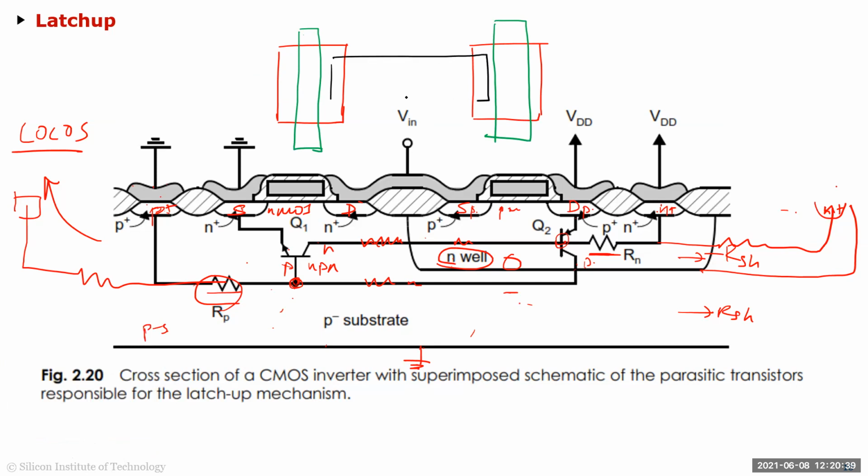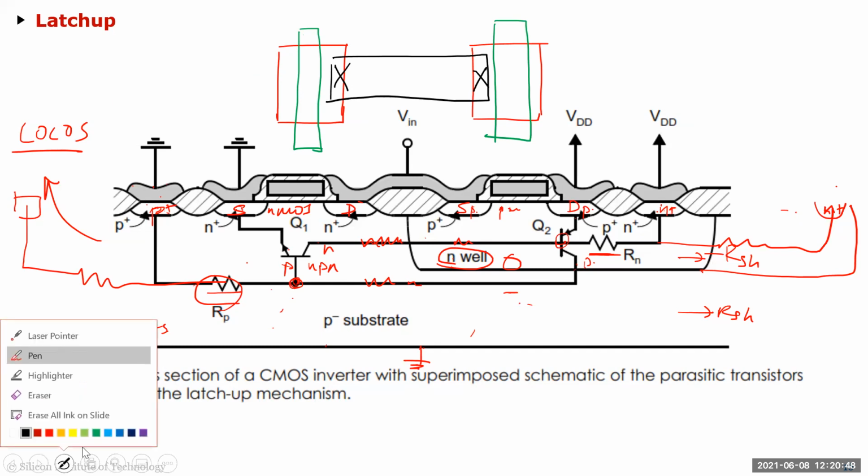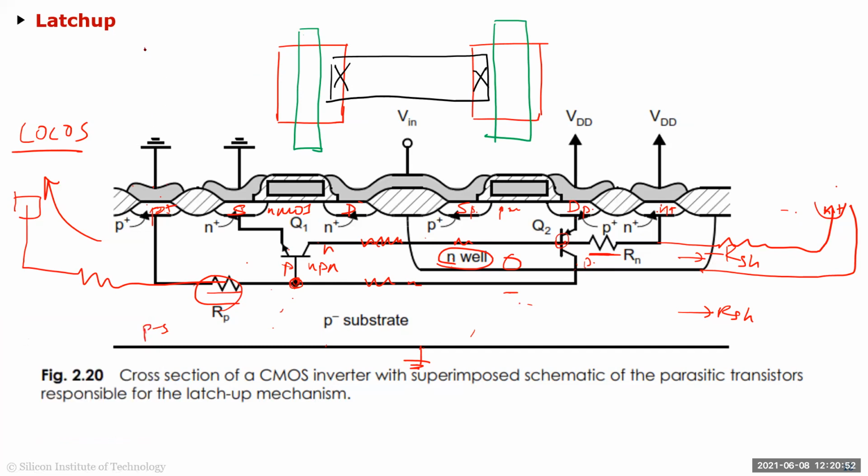You drew layout yesterday, so you did a via here, this is metal 1. And then you did substrate connections, which is basically adding a P plus diffusion here, and then you added an N plus diffusion here. This is N plus, that's P plus.